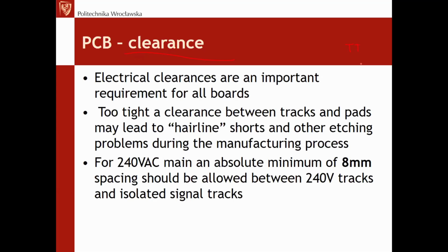There are certain norms that I don't want to go very deep into. But for example, for 220 volt AC mains power supply, the spacing between tracks should be about 8 millimeters. It's an absolute minimum between tracks if the tracks are not insulated, if there is no protective layer.